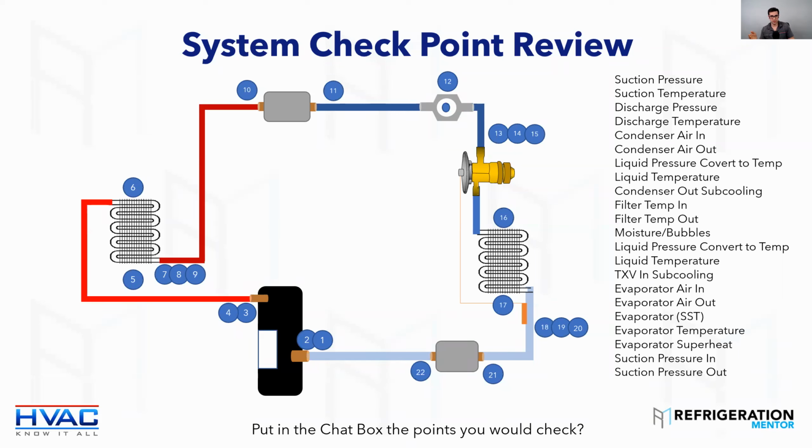Most technicians don't. Now, if you're talking about a little small system, the acid test might be more than the system itself. Okay, but when you're talking about larger systems, you need to check that stuff. You need to put it in your quote. You need to write it down that I need a follow up to remove the filter dryer, and then do another check, especially if you had a bad burnout or electrical failure.